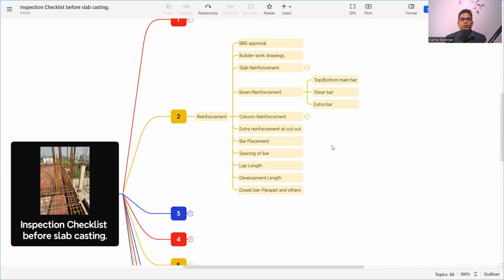So that's why we need to check whether the splices zone is as per the design or as per the document or not. So how to check the beam splices zone? I have made a detailed video on that. Check there or in the description. You will get an idea of what the beam splices zone is and how to calculate it. So we also need to check whether the lap or the splices are in the splices zone and not in the non-splices zone in the beam reinforcement.